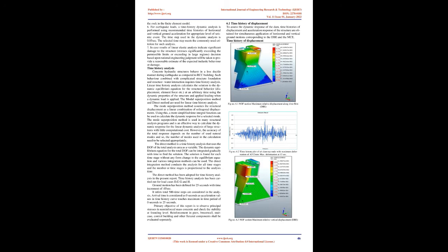Deformation and stress results are obtained for each time step and maximum values are extracted to be combined with the corresponding values from the static load cases. The following general postulates have been considered. 1. The stress is proportional to strain and the material follows Hooke's law.